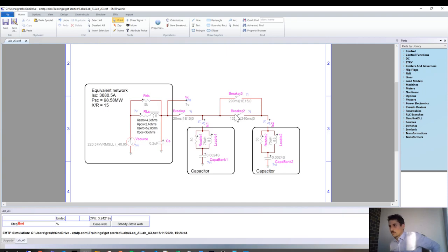However, sometimes you just cannot. It's just not your decision. For example, the circuit breaker opens when the current stops, and the voltage across the circuit breaker will be, like I said, 1 here minus 1 here, so 2 per unit. And that's a moment, if the circuit breaker is not open completely, where there could be a restrike. And if there is a restrike, then basically you will have an even worse case. So you will have an even higher transient.